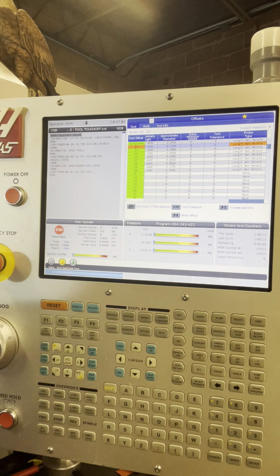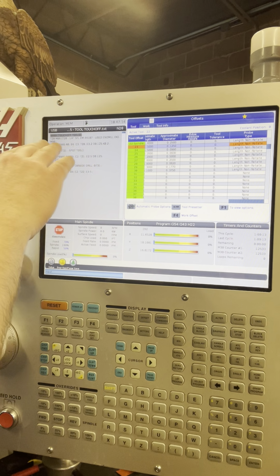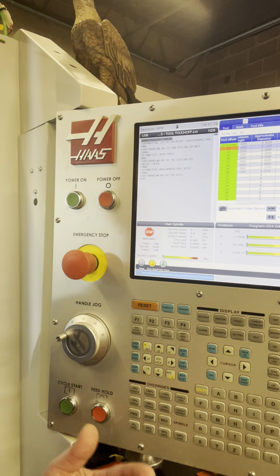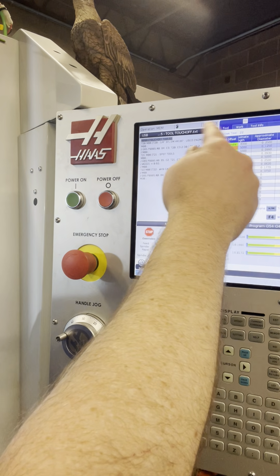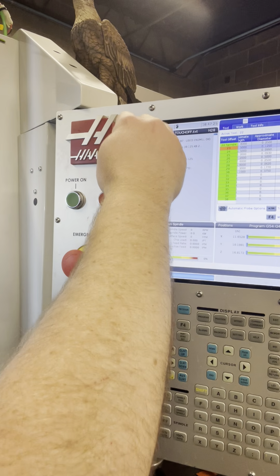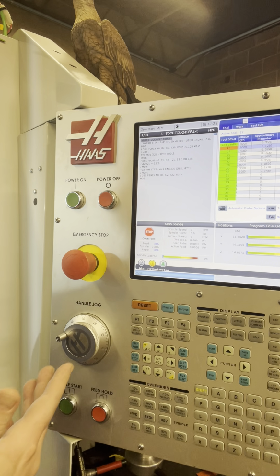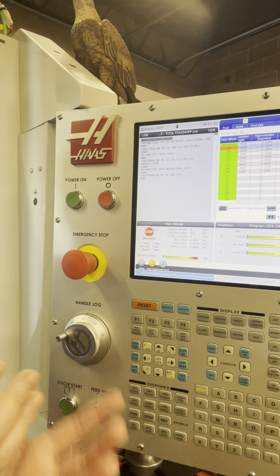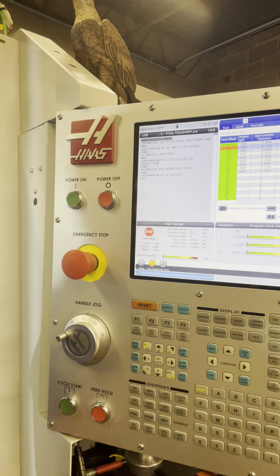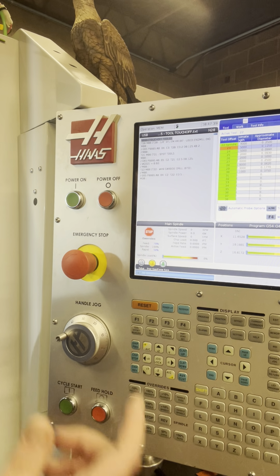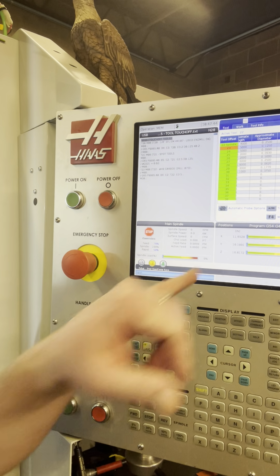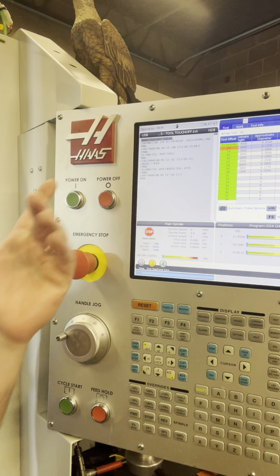But when you do that, it writes into MDI, and that's where I got this idea from. It writes out all the tool touch-off commands in here, and it has tool changes in there, so it'll go down your list and do each tool one at a time. This is all written out, but I thought if we did this, we could put M0s in here, so when it does tool 20, it'll pull up tool 20 and then stop and wait for me to either load the tool or make sure it's in there. Then I can hit cycle start, and it'll do the tool touch-off, which is written in there. Everything you're filling in here is basically converted into the code.